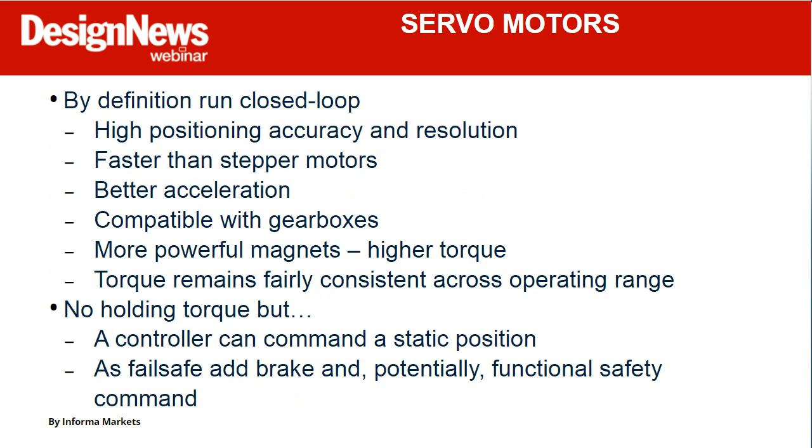On the other hand, you've got servo motors for your very high performance applications. And again, by definition, a servo motor runs closed loop. So you're going to get high positioning accuracy and resolution. Although I do need to wave the flag here, folks, on feedback. Getting super high resolution feedback is not necessarily going to give you super high resolution motion.